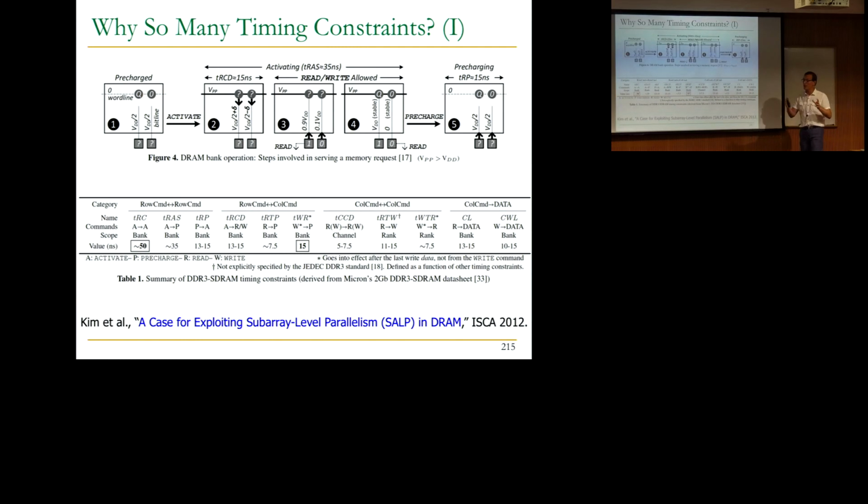And going forward, that may be a much more flexible interface, but it's not clear if that's going to change. So hybrid memory cube, for example, that we're going to discuss later on, has that sort of interface. It's more packet-based as opposed to these timing constraint-based. And if you go to an asynchronous interface, you can specify many things potentially, right? You can say, DRAM, I'm going to ship you this function. If you have the capability, do it. Otherwise, send me a negative acknowledgement. And the DRAM says, OK, I can do it, and I'll let you know when I'm done. So that interface doesn't exist.